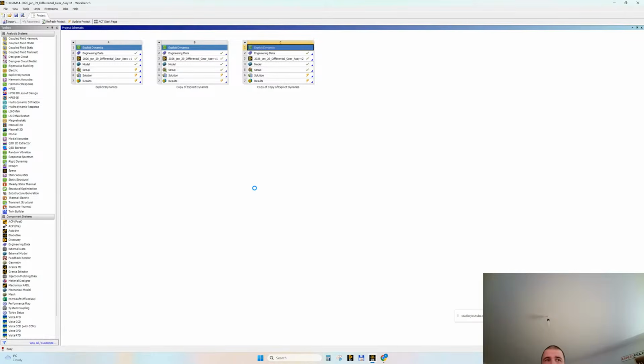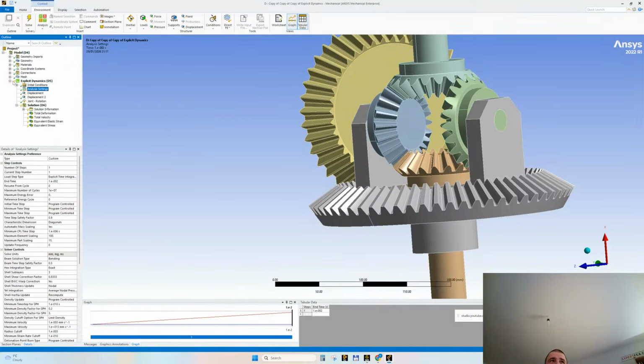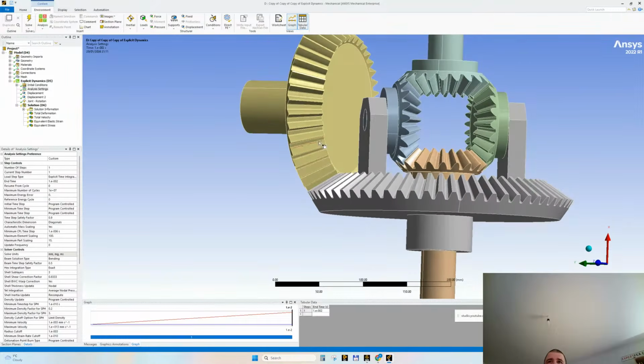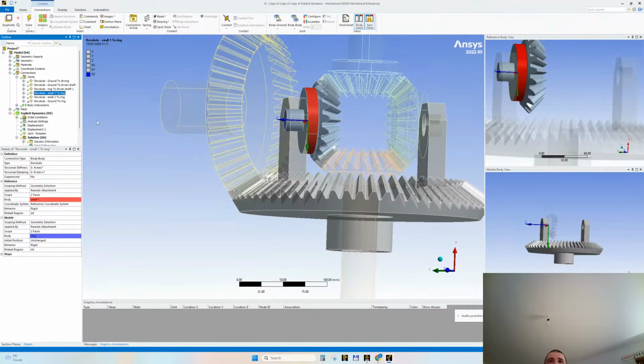So yes, in principle it should be done with realistic end time. I was kind of anxious to show a very easy approach with explicit dynamics because I didn't want to use the contacts. And in doing so, I have imposed a very small end time. And this affected the stiffness of the entire assembly. What we can do is maybe leave this end time and decrease a little here. Maybe make it 90 degrees. And here, let's leave it as it is.